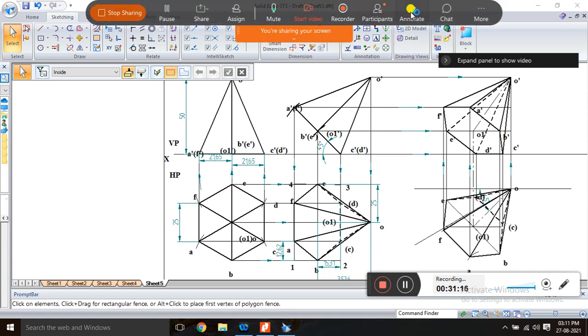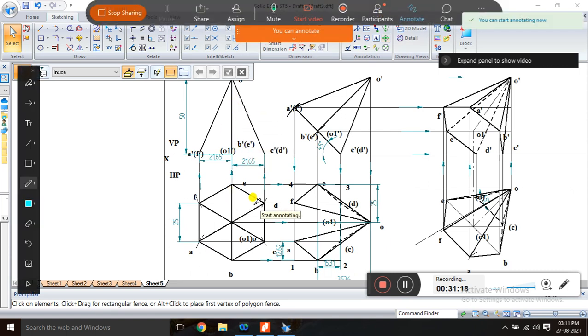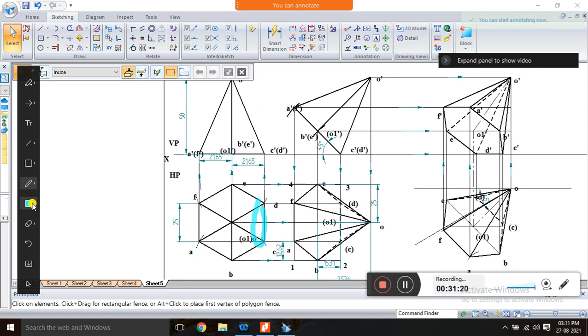So like this you have to construct the first position. So first position with the edge condition, okay, and pyramid. Second position, axis at 45 degree, but we take a base inclination, base is equal to 90 minus axis inclination, so that you use the 45 degree. Then reconstruct and you will get the second position top view. And in the third position, it is a beta angle. First draw 30 degree, then find out the beta angle of 45 degree. Once we got the beta angle, then reconstruct the entire thing here with the help of the box method.